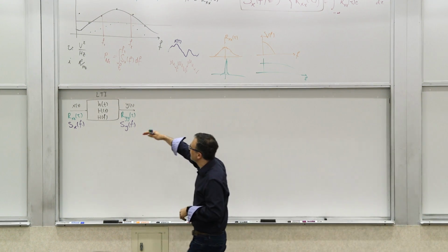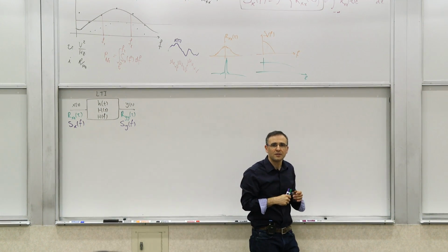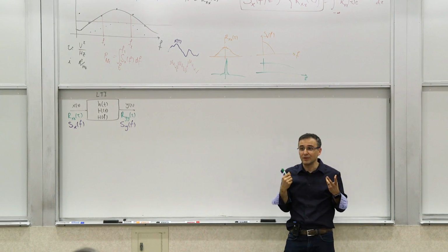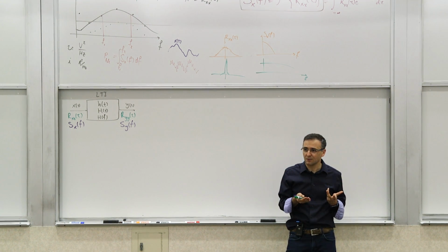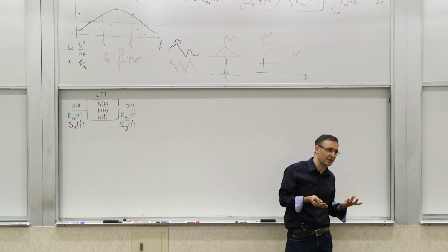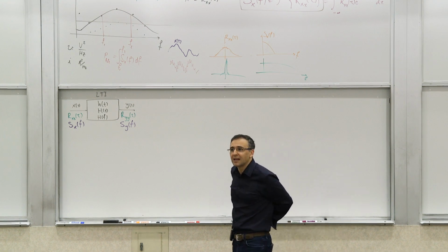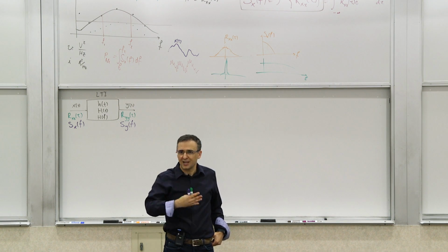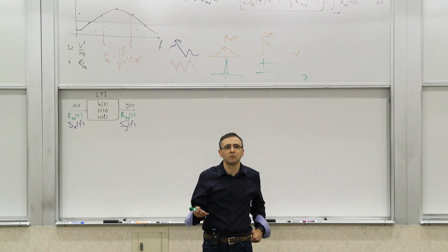So that's in time domain and frequency domain. So this is Sx of f, a function of frequency. Now, this is the key question, because if we know this, then we can say if there's a simple relationship we can define between the power spectral density of the output and the power spectral density of the input, or the autocorrelation of the output versus the autocorrelation of the input, and the response of the LTI system, then all of the analysis that we've done for calculation of the circuits and the transfer functions, all of these techniques can be useful. Because now we can use them to know what the evolution of the noise would be from the input to the output.